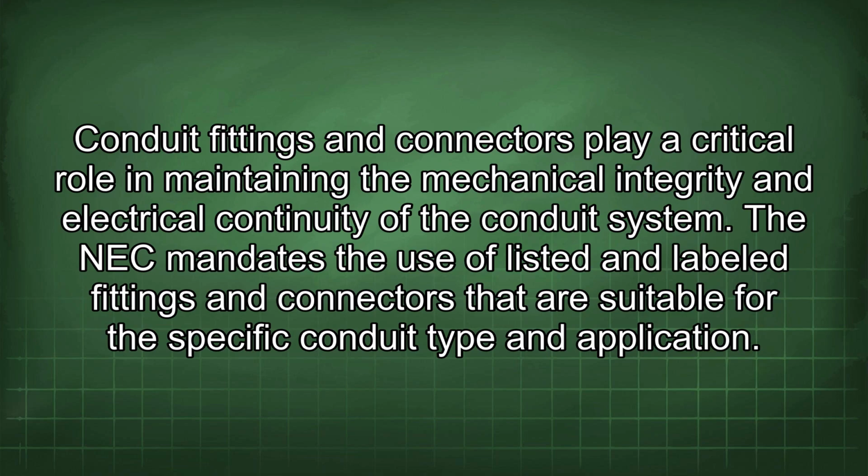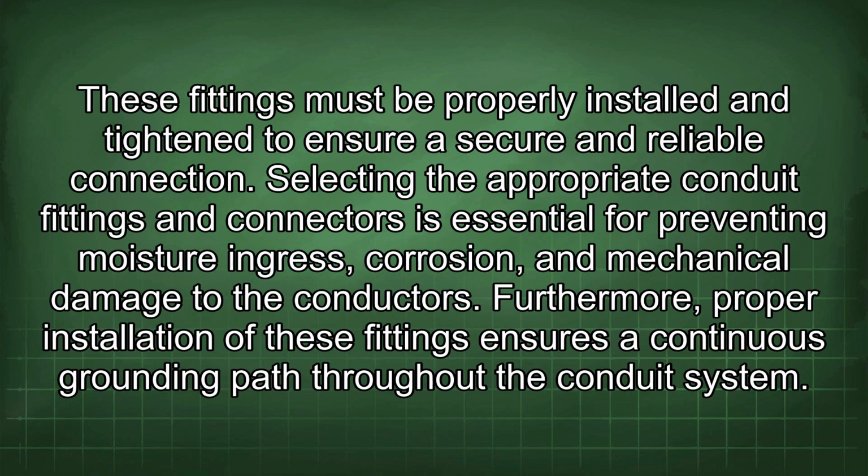Conduit fittings and connectors play a critical role in maintaining the mechanical integrity and electrical continuity of the conduit system. The NEC mandates the use of listed and labeled fittings and connectors that are suitable for the specific conduit type and application. These fittings must be properly installed and tightened to ensure a secure and reliable connection. Selecting the appropriate conduit fittings and connectors is essential for preventing moisture ingress, corrosion, and mechanical damage to the conductors. Furthermore, proper installation of these fittings ensures a continuous grounding path throughout the conduit system.